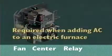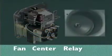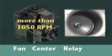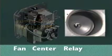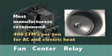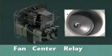Another component is the fan center relay, required when adding air conditioning to an electric furnace. This relay energizes the blower at low speed for heating and at high speed for cooling. Most manufacturers recommend 400 CFMs per ton for both air conditioning and electric heat. So, that's a quick overview of the components used in electric heat systems. Now let's watch a technician use his troubleshooting skills to solve a problem with electric heat.